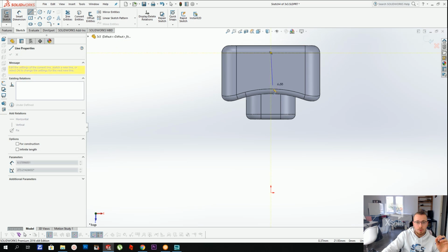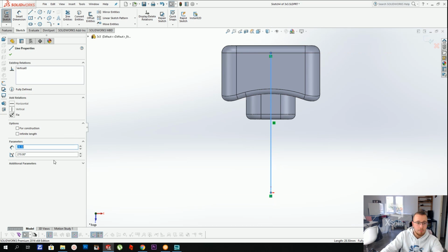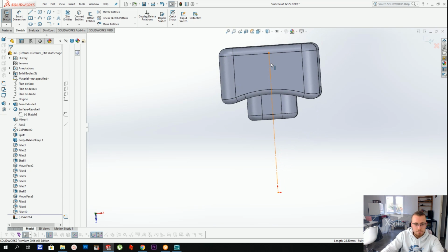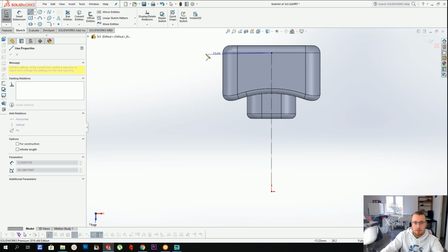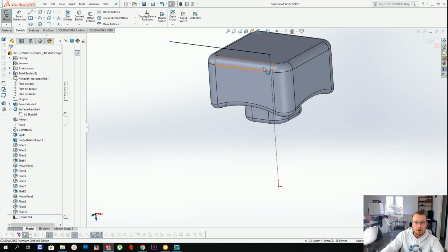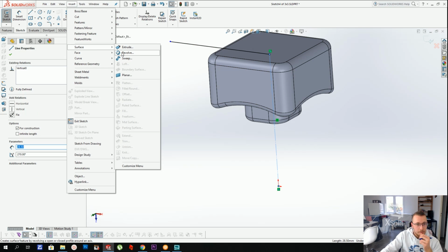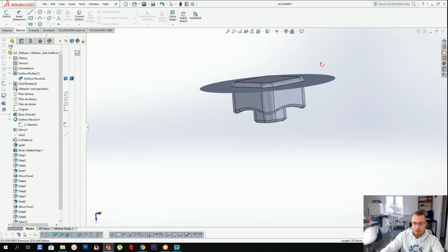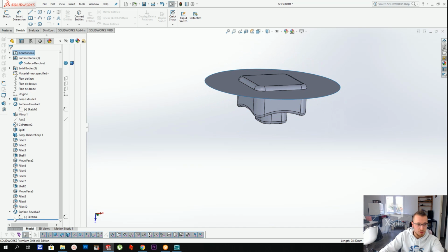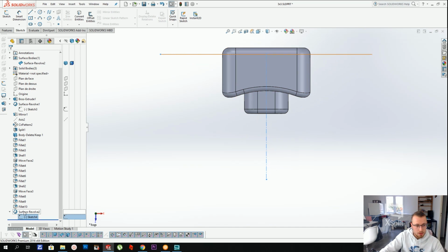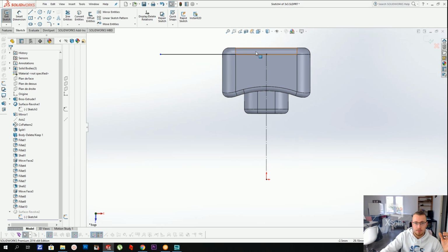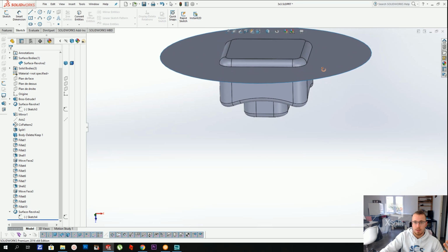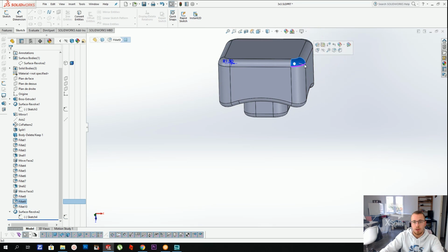What I'm going to do is create a surface with which I'm going to cut the cap off. So here's the axis, which goes straight through the center of the part, and I've got this line right there that we're going to revolve around that axis. And boom, this is your surface. Now there are other ways to do this, but I just like this one because you're essentially drawing a sketch, and you can create a line that intersects this piece at the bottom of the fillet. So essentially you don't really see that it's a fillet afterwards. I just like cutting it along that line right there.